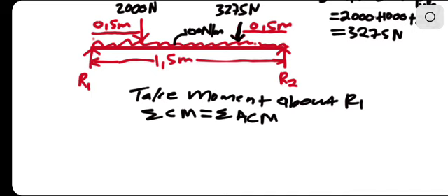Okay, the forces that are acting clockwise: the 2000 will cause the beam to rotate in this direction, and also that one will cause the beam to rotate in this direction. Remember, here in the middle we'll also have the weight, the distributed load. When you convert it, you'll have the force again that will act like that. So you see we have 3 forces that will cause this to rotate clockwise.